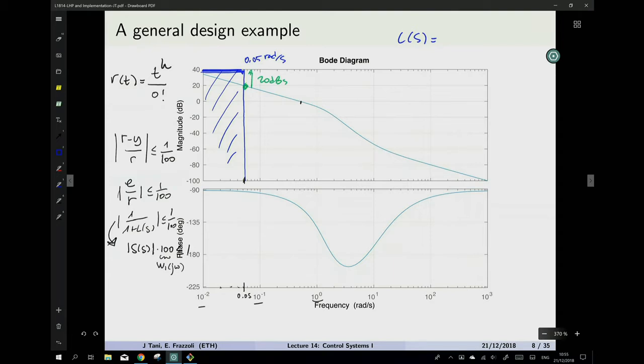Exactly. You can calculate. I mean, if you have the nice squared paper in front of you, you can tell more easily, but you can calculate it by 20 dBs. So we want a K of 20 dBs, which means a gain of how much? I mean, when we write the controller, we have to write it in linear. Please don't get confused between bouncing between linears and dBs, because it's a very common error, and it's a pity because there's like, yes, 10. Gotcha, okay. That only putting C of S equal 10 satisfies our first tracking error specs.